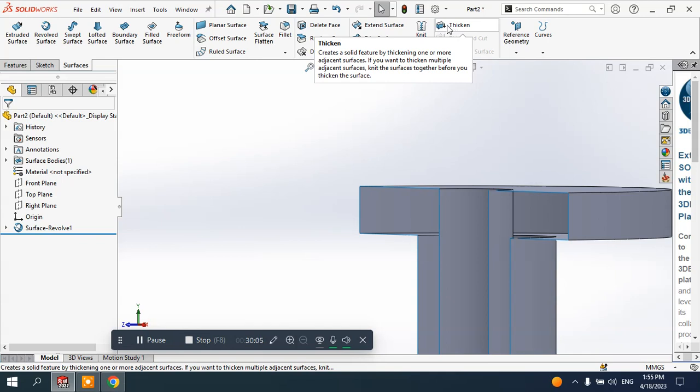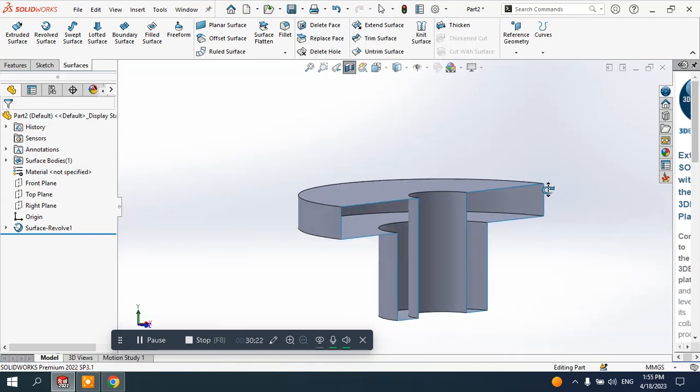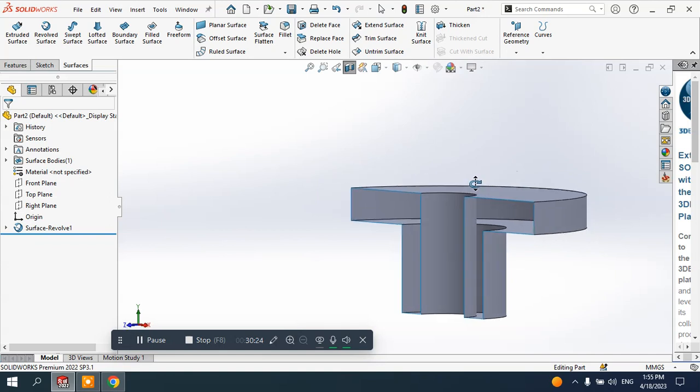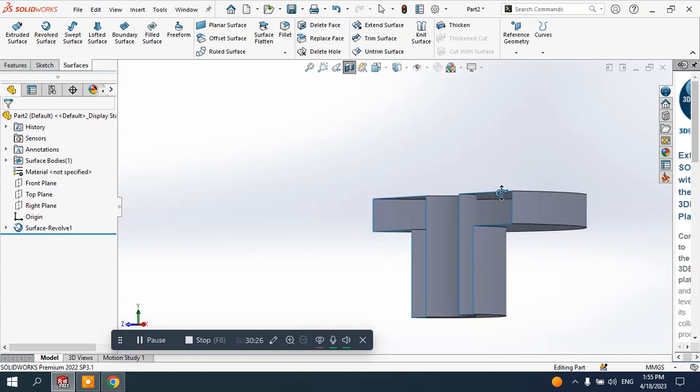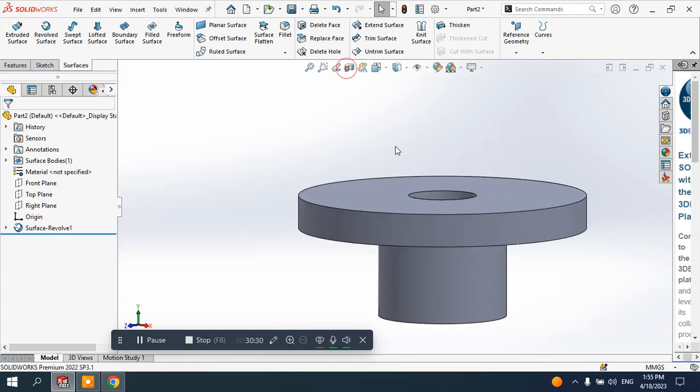OK, just now we are creating just the basic shapes, then we will convert these shapes by giving some thickness, so we will convert to a plastic element. So we will see it step by step. This is just the basics now. So here you see it is open, there is no material inside, so it's a thin wall. I will click the section view.